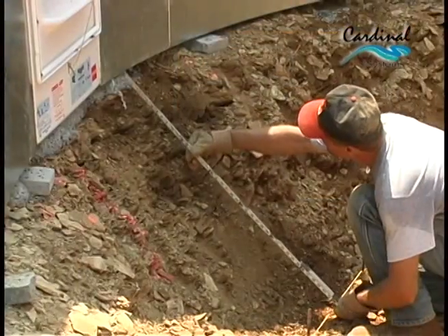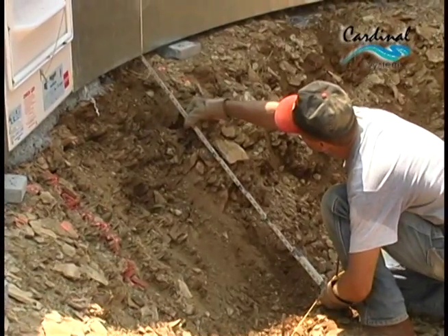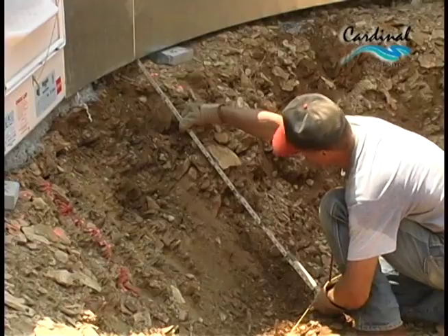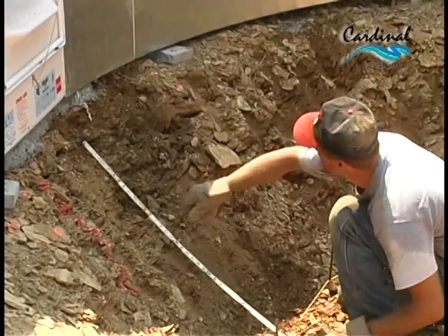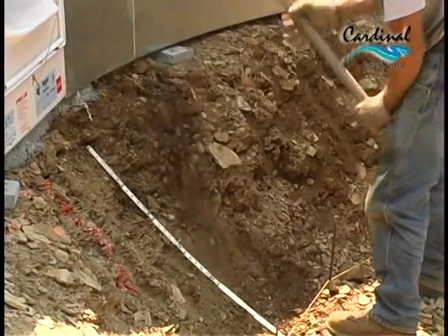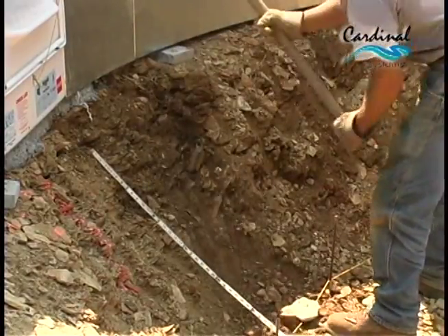By running a straight edge from the bottom of the panels to the string, you can determine high spots that need to be trimmed as you shape the hopper. Run the straight edge along until you hit a high spot. Then use a pick or shovel to remove the obstruction so that it doesn't protrude beyond this point. You'll perform this trimming all around the entire pool.